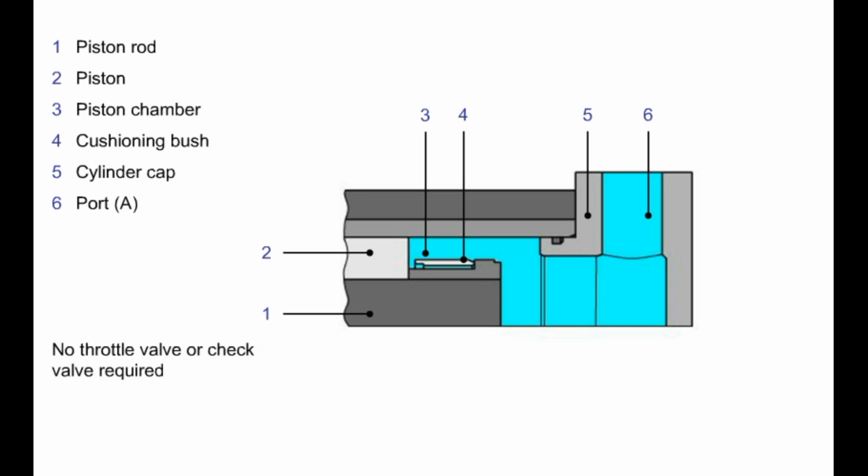This type of end-position cushioning system provides gentle extension and retraction even during startup conditions, and therefore protects the working device, load, and the cylinder components from damage. During the system operation, the end-position cushioning setting does not need to be checked or reset, thus the system is maintenance-free. In the next screen, we will examine the operating principles by means of an animation sequence.